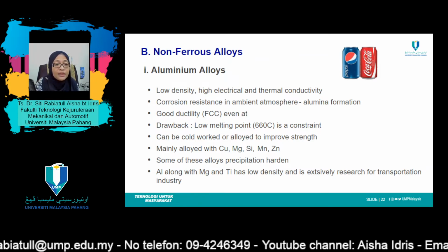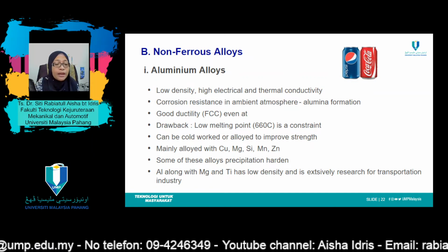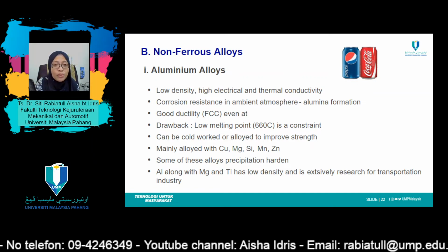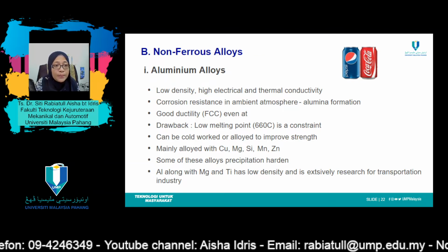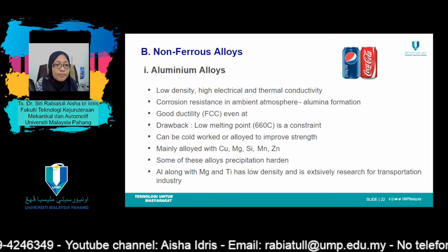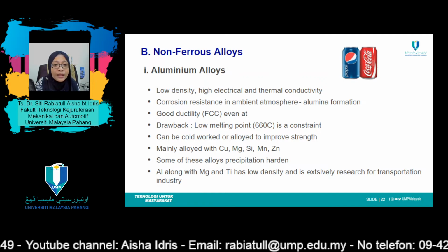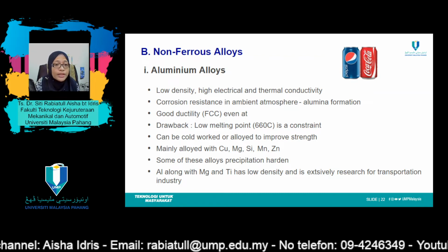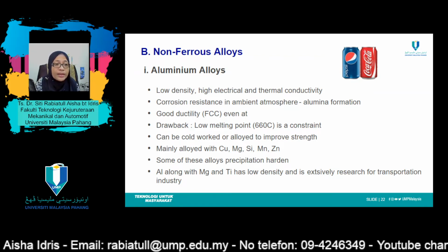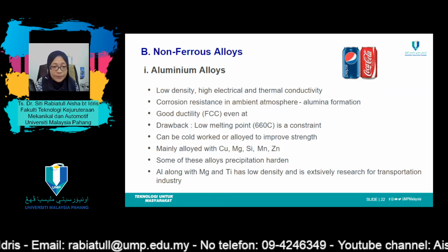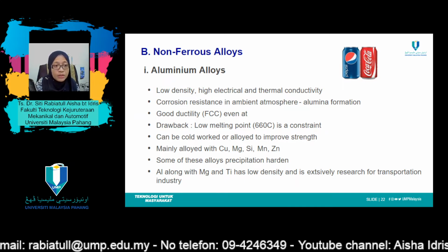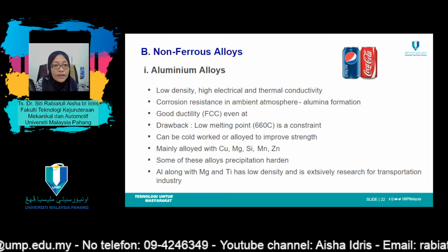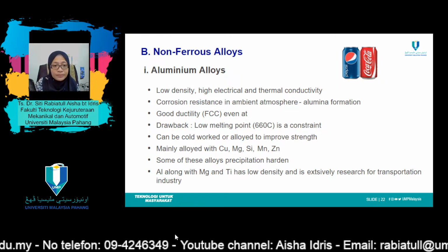The mechanical strength of aluminium may be enhanced by cold work and by alloying. However, both processes tend to diminish resistance to corrosion. Principal alloying elements include copper, magnesium, silicon, manganese, and zinc. Non-heat treatable alloys consist of a single phase, for which an increase in strength is achieved by solid solution strengthening. Others are rendered heat treatable as a result of alloying.